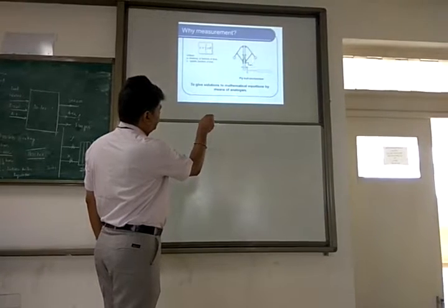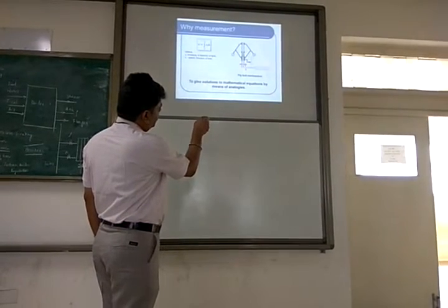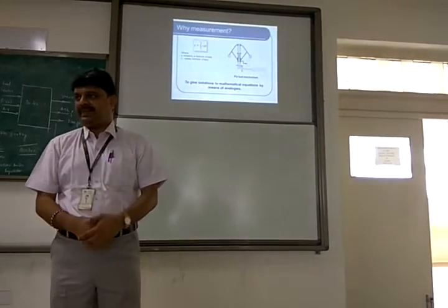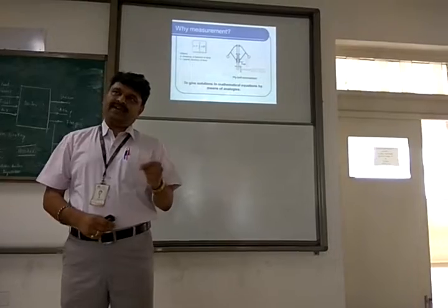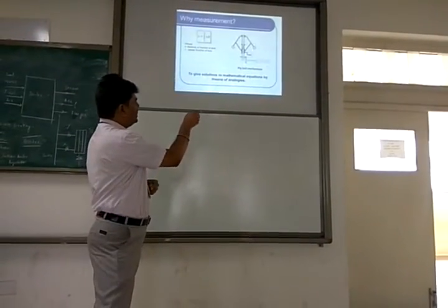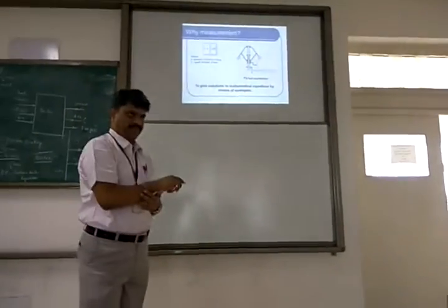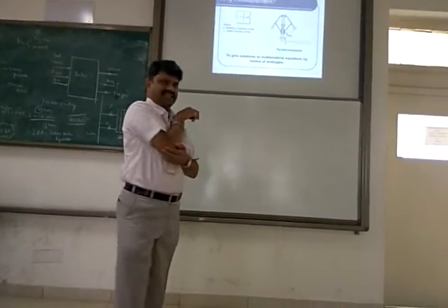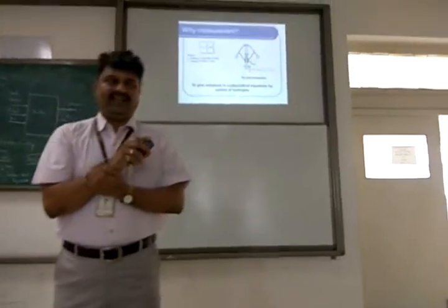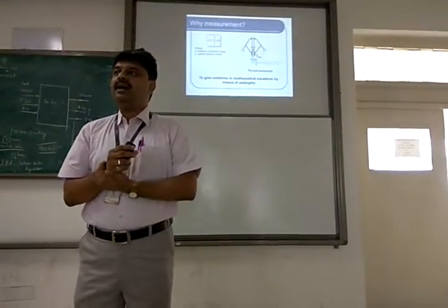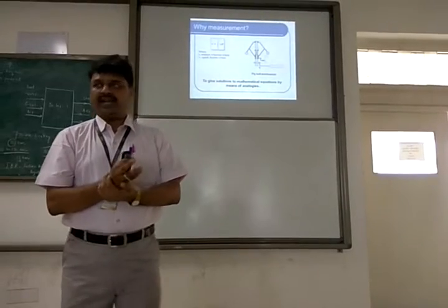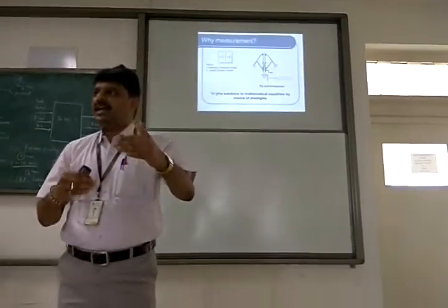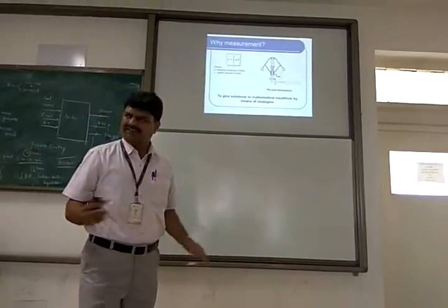So that is the instantaneous velocity. And then here you have two bevel gears connected to a mechanical counter, which counts the number of rotations it has made. So the number of rotations you will get here, and the instantaneous velocity you will get here. You have the basic relation: x is the integral of v dt, where x is the displacement and v is the velocity. If you integrate velocity, you will get displacement for a given time duration t1 to t2. I think these are all fundamentals, you know it, right?